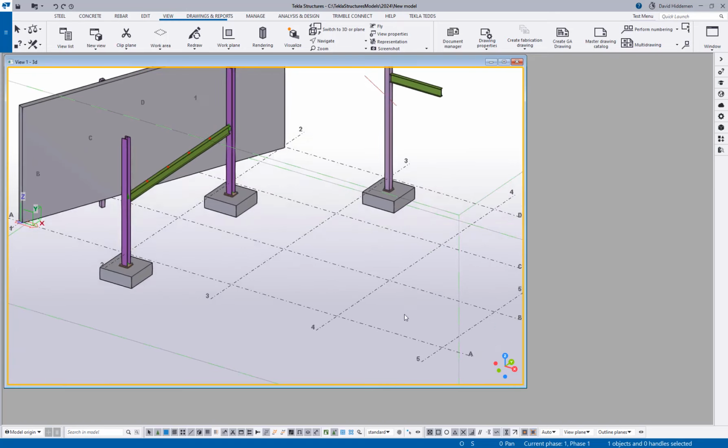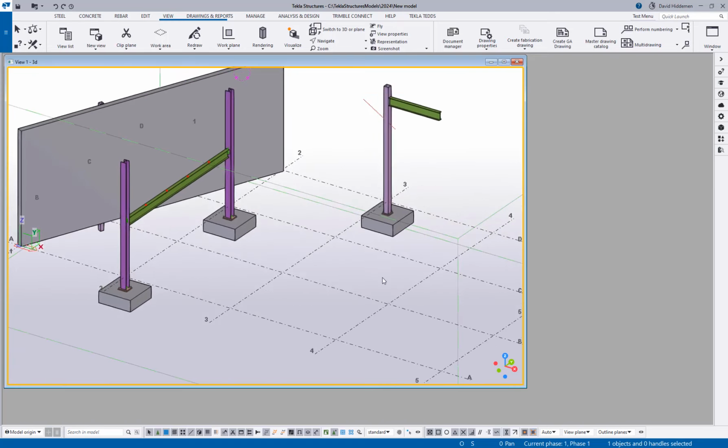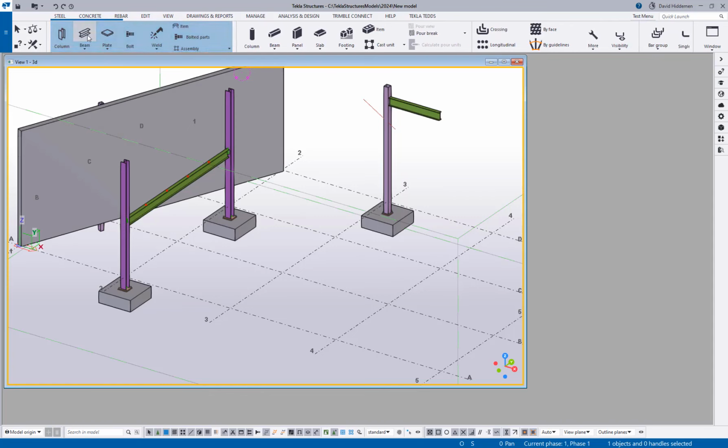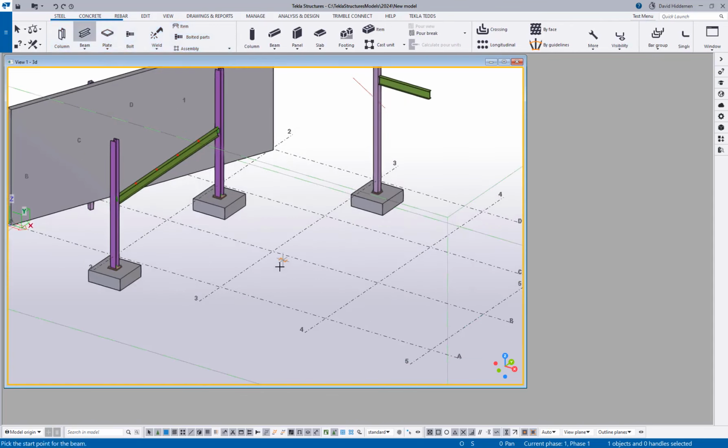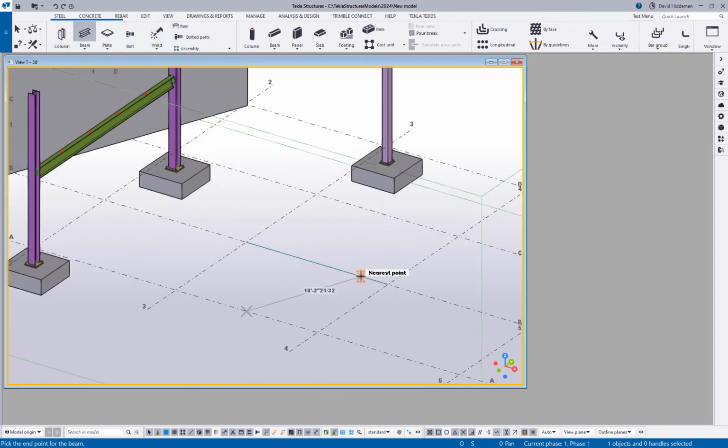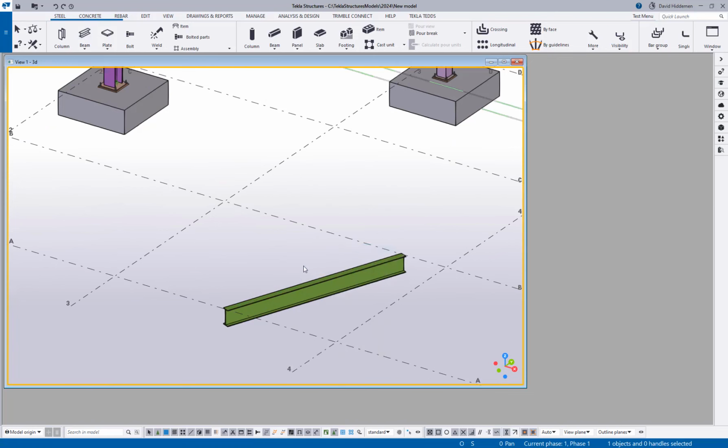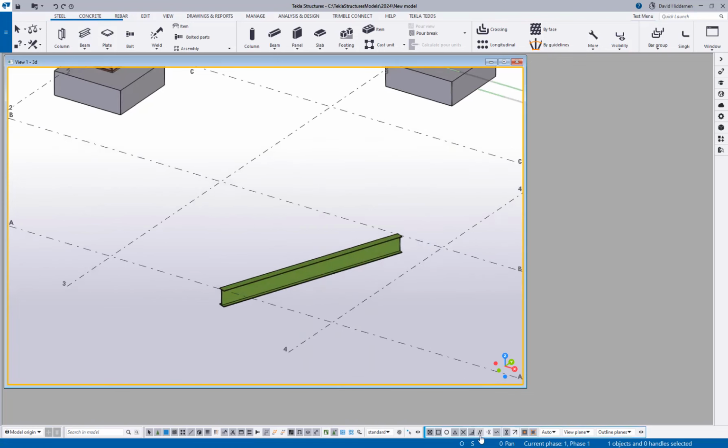So today we're going to be talking about a couple of new snapping tools in Tekla Structures that I think is going to make modeling, especially complex stuff, a little bit easier. The first one that I want to talk about is snap to parallel. So let me go ahead and snap in a quick, skewed beam here just for fun. Down here you'll see on the toolbar there's a new snap to parallel points icon.